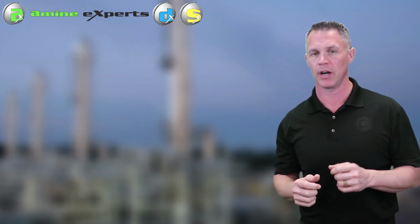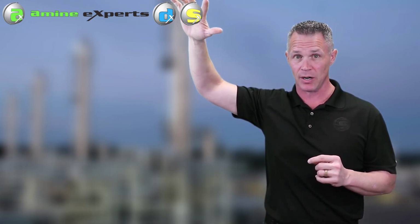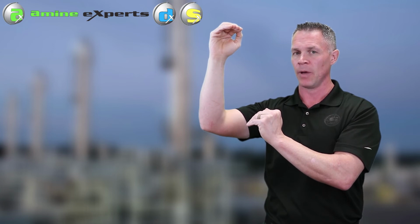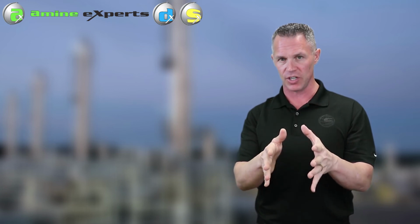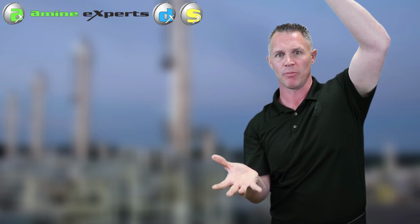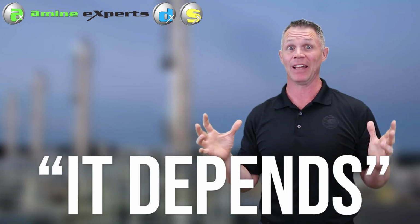Now, I will give one more scenario, and that's where there's a compressor after the amine absorber. When we have a compressor, we're going to have a knockout drum right before the compressor, and it's going to have not just a high-level liquid alarm, but a high-level shutdown, because we definitely don't want liquids getting into a compressor. In those situations, foaming would be worse than going high on H2S, because foaming would cause amine to carry over, fill up the knockout drum upstream of the compressor, and shut the whole plant down. So the overall answer to what should my lean amine temperature be is, well, it depends.